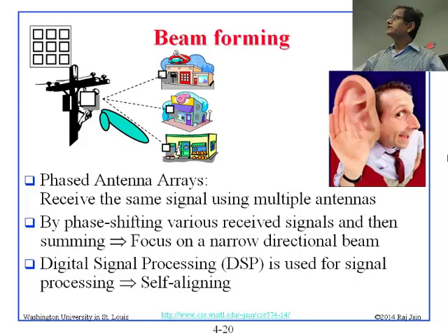Okay, so this picture here shows multiple antennas. I have shown here 3 by 3. It could be 4 by 4. So there are 9 antennas shown here in this one little area, but it could be any number. And the idea is when you have all these antennas, all this multiplication in the frequency domain and all that requires Fourier transforms, like we said before. And all that Fourier transform is done in digital signal processing, DSP, units. And so basically by calculating that, they can figure out exactly when it is totally aligned.